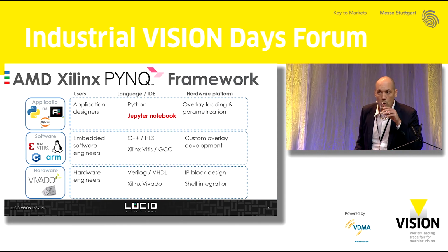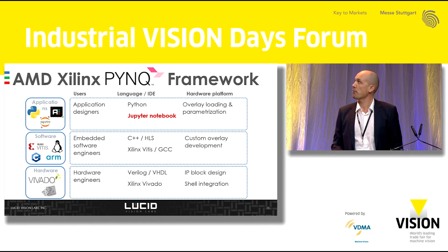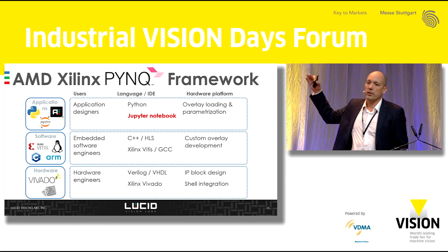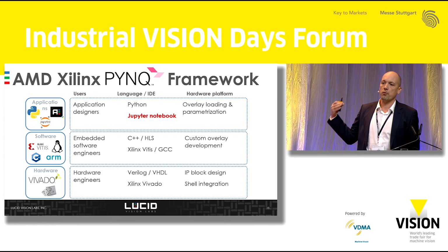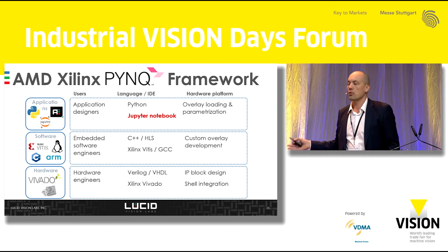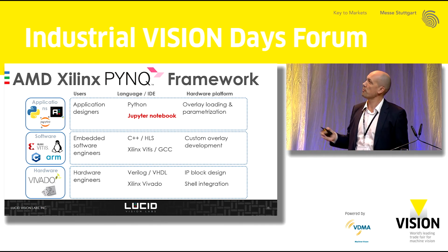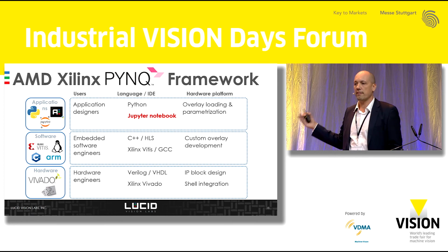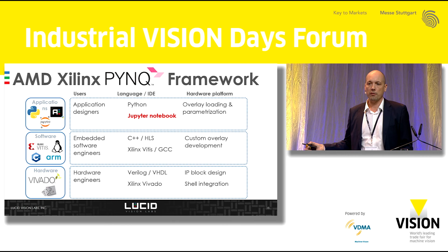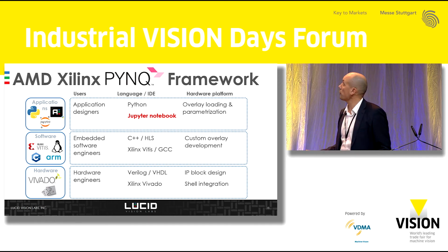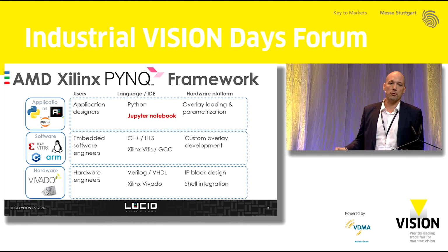So sorry. PYNQ stands for Python Productivity for Zynq platform. It's a framework that lets the user access the device and program the device at different levels. From the lower level, the VHDL programming for FPGA engineers, to mid-level with high-level synthesis using the Vitis development software, and providing at the edge on the device a Jupyter notebook interface that lets you connect to the device. So out of the box, it comes with its own quick development environment where you can load, configure and parameterize various FPGA processing and just use them to test your solution.